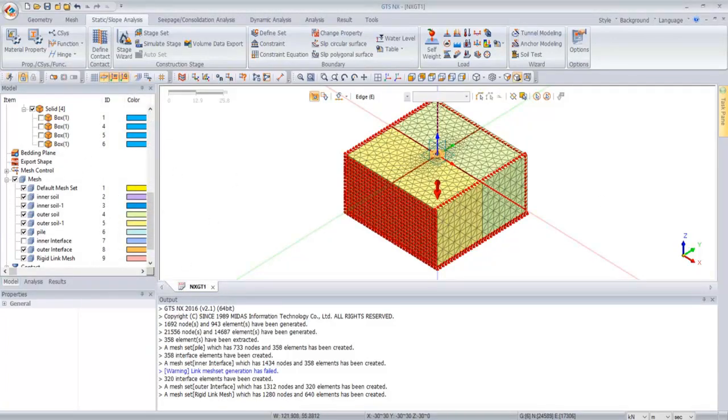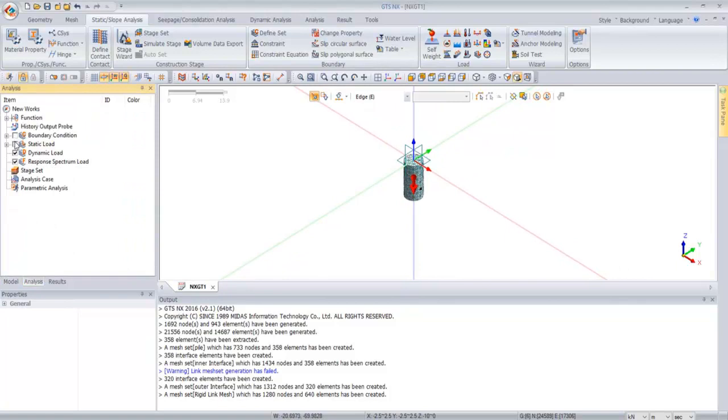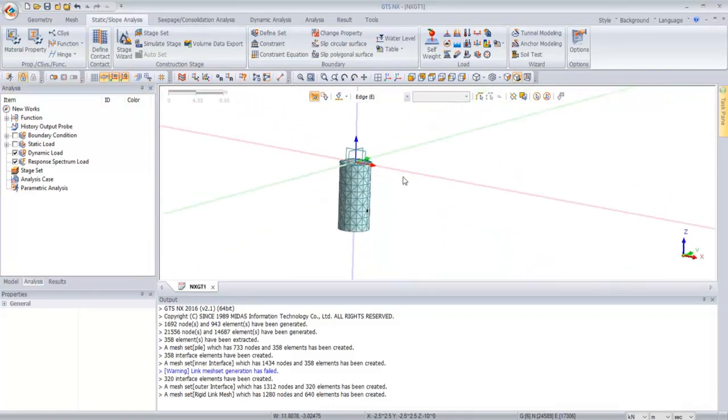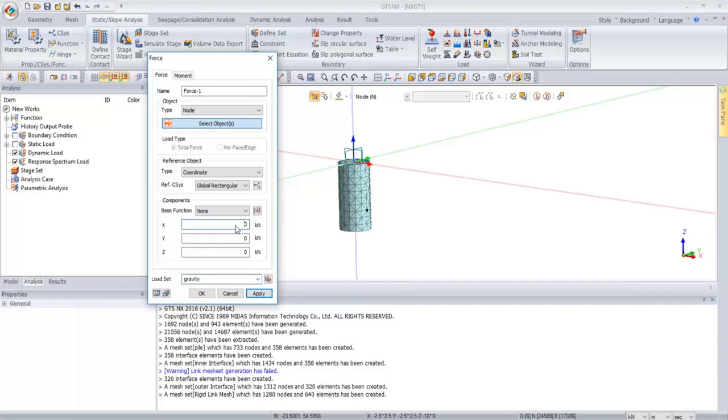And now we're going to get very specific with the point load. As we had mentioned, we're going to apply a force specifically to model the interaction with the chain, the pull force from the chain itself. And we're going to create 4 sets of force loads, and we're going to vary the magnitude in the X and Z direction to create different angles of pull. So we're going to create the first one at 30 degrees.